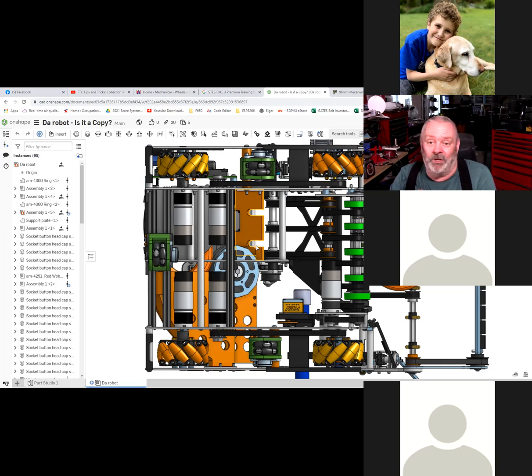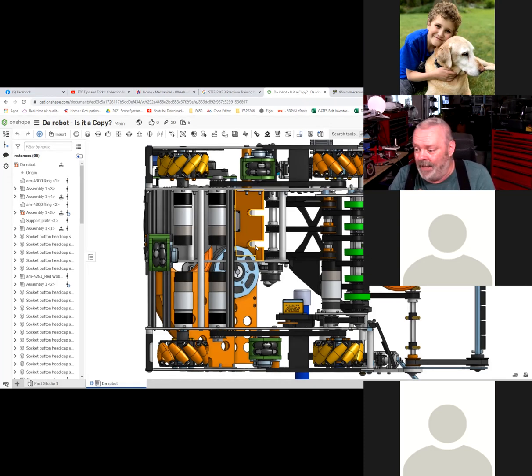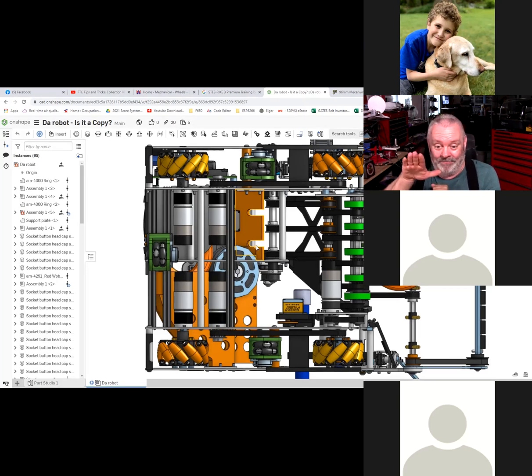So Anand, you asked a very good question. Why would I choose one over the other? A super great question. Part of it is cost, and part of it is actually, quite frankly, the game. It turns out that the wheels that have these roller mechanisms on them tend to not work super great if you're on a ramp. If you have to drive over something uneven, they don't steer all that well in those situations, because they're working on opposing forces. So these are really great if you're always going to be flat on the floor.